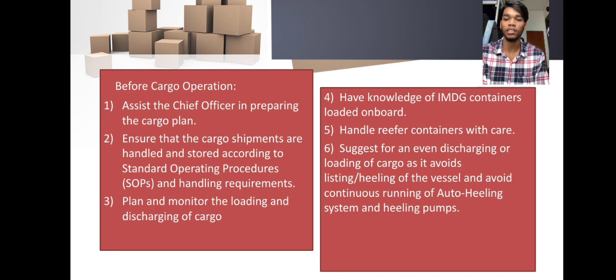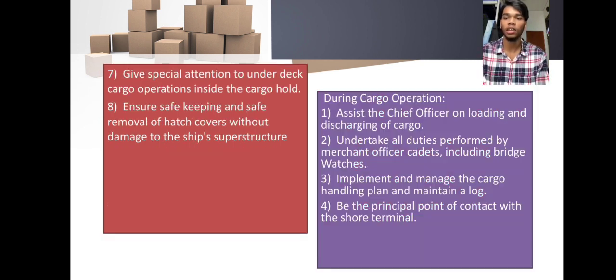For the first, before cargo operation, assist the chief officer preparing the cargo plans and ensure that the cargo shipments are handled and stored according to standard operating procedures as well as SOPs and handling requirements. Plan and monitor the loading and discharging of cargo and have knowledge about IMDG containers and handle reefer containers with care. Suggest in even discharging or unloading cargo that itself is heeling of the vessels and avoiding continuous running of auto heeling system and heeling pumps. And give special attention to under-deck cargo operations inside the cargo hold and ensure safe removal of hatch covers without damage to the ship superstructure.